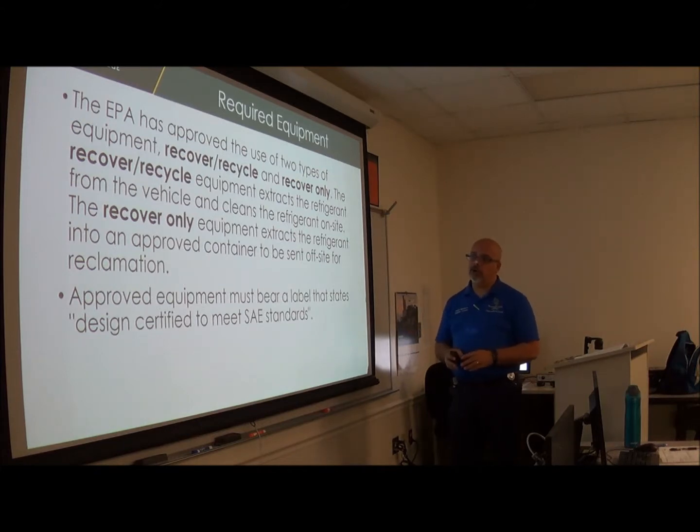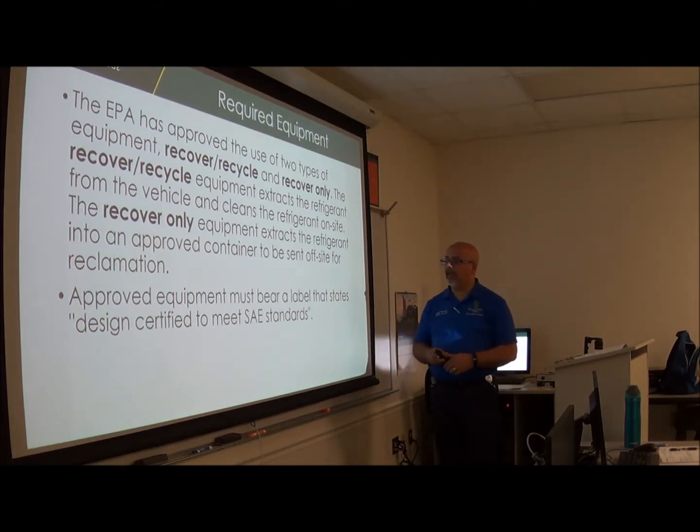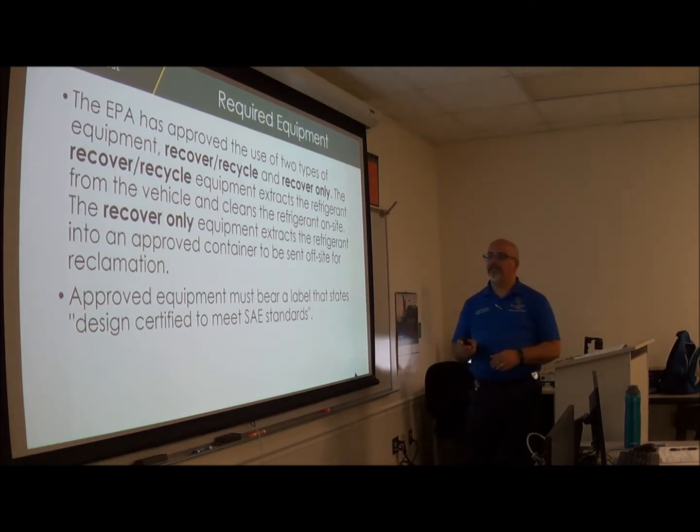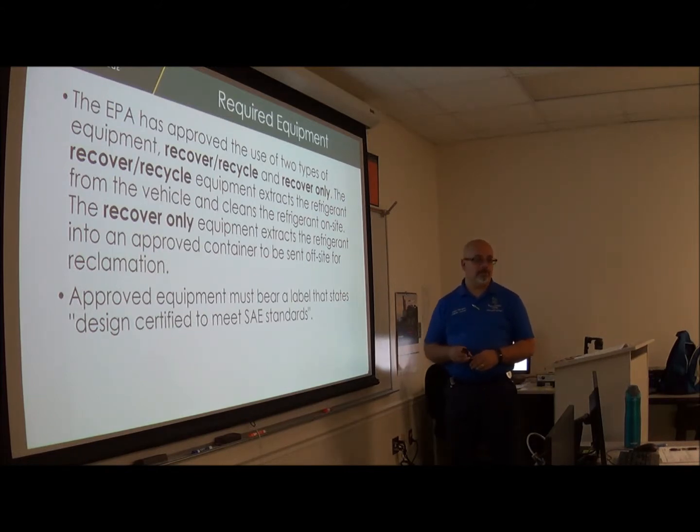The Recover Only equipment extracts that refrigerant into an approved container to be sent off-site for reclamation. Approved equipment must bear a label that states designed certified to meet SAE standards. So it can't be put into any container, and the approved container must have this label on it.